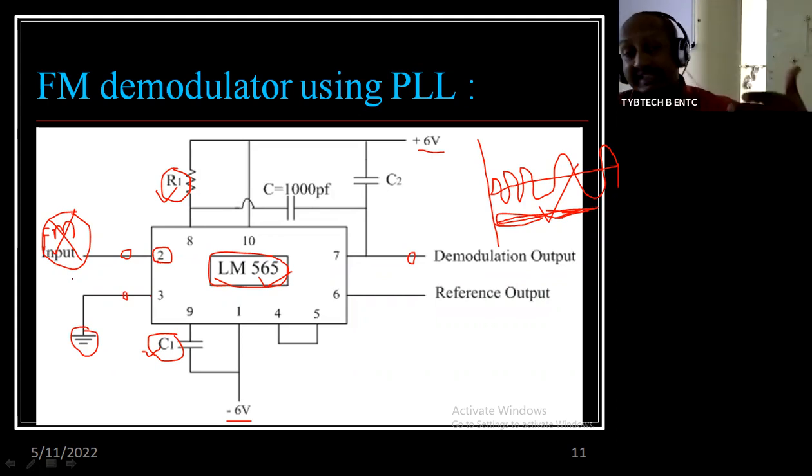Even if the input frequency is 10 hertz but it becomes 11, 9, 11, 9 due to some reason, here the output is going to remain the same, that is 100, 100, 100 accordingly. So this is how it manages the constant output of this particular PLL. That is the main function of the PLL.